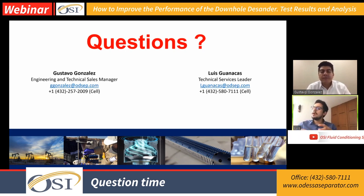The material of your desander. Secondly, you need to be aware of the production you are expecting. I mean, if you are producing X value and you are expecting a Y increase, you need to get a proper helix. However, it is really difficult to pull the well just to change the helix, right? So that's why I'm telling you, keep in mind the material is going to highly affect the longevity of your well downhole. That's one of the things.